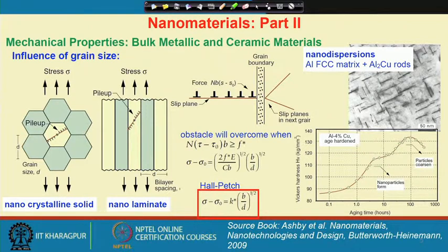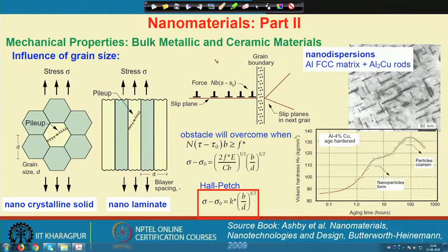Now, the second part: is there any effect of such a small grain size, and what is the effect of reducing the grain size on the strength? The strength in a material is usually explained in terms of dislocation pile up, like the Stroh pile up model, and we can simply think about a microcrystalline sample with a grain diameter of d.